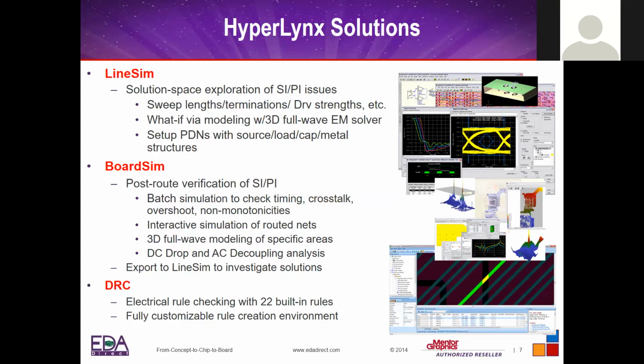And where do you use electrical DRCs? If you have one or two designs per year, roughly, then you have a lot of time to look at your board. But if you're in the business of producing 5 boards, 10 boards a year, or more than 10 boards, you may not have the time to do signal integrity or power integrity analysis for all of these boards. And oftentimes these boards may be designed by an external contractor or design house, not in-house. So how do you know the quality of these designs before you actually build them or power up? If there's a way to quickly check for any electrical violation at the high level, then at least you can identify these problems before committing to those designs.